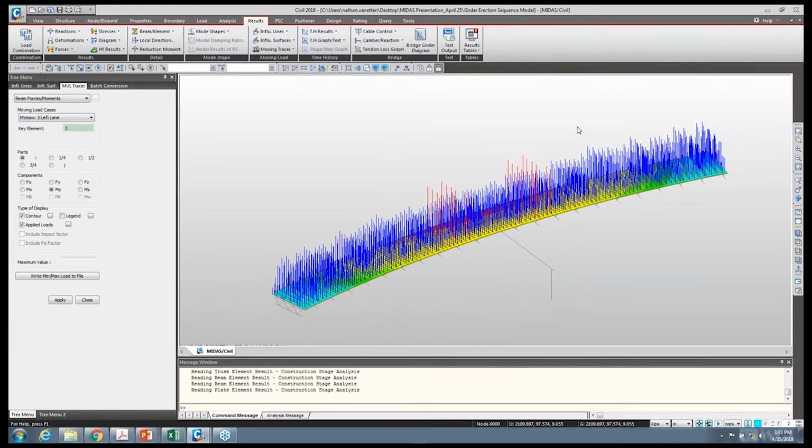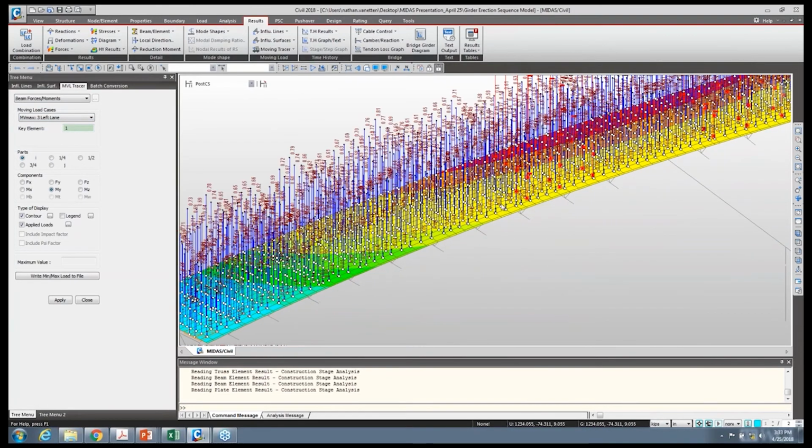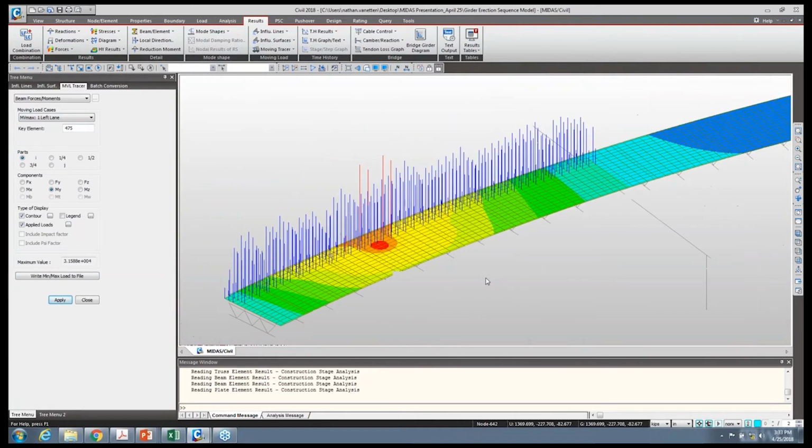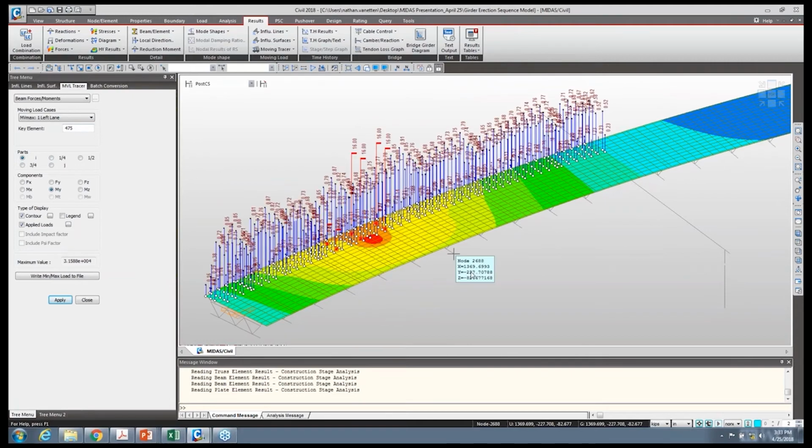The things to highlight is that we have to evaluate for stability for construction use under wind loads, and also temporary construction loads per other criteria of the SDG, which is the Florida Structures Design Guidelines. But the other interesting thing about what the state of Florida requires, and I've seen in other states, is that for all steel girders and for bridges on false work, include in the plans a workable erection scheme that addresses all major phases of erection, investigate superstructure stability at all major phases of construction, consistent with the erection scheme shown in the plans, show the required temporary support locations and associated loads assumed in design.